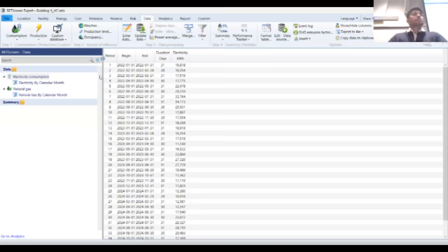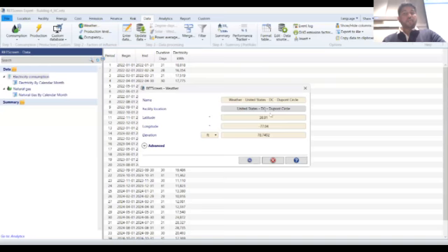To do that, first, I need to understand what are the factors that affect my energy consumption. What are the factors that affect electricity and natural gas? The single most and the primary factor that will influence electricity and natural gas is going to be weather. So we need to add the weather data in to form a good baseline, right? So on the top there's a button called weather. I click on weather, it automatically pulls the coordinates because we've established the facility, which is in Washington, DC.